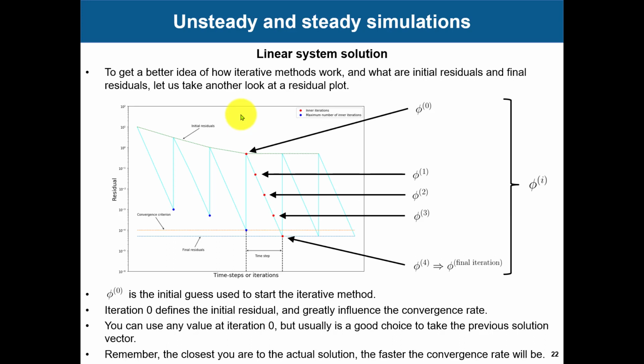Something about the initial conditions as well, and the iterations and those residuals. This is important. I don't like to look at the residuals because sometimes they can be misleading, or hard to interpret. You need some experience to know what is going on, because the first time you start to do CFD, you will expect that your residuals need to go to your tolerance, 10 to the minus 3, 4, 5, whatever. But have in mind that those tolerances that you are setting there are initial residuals.